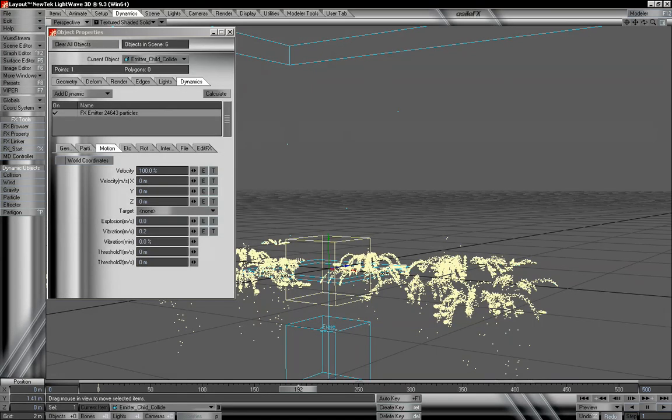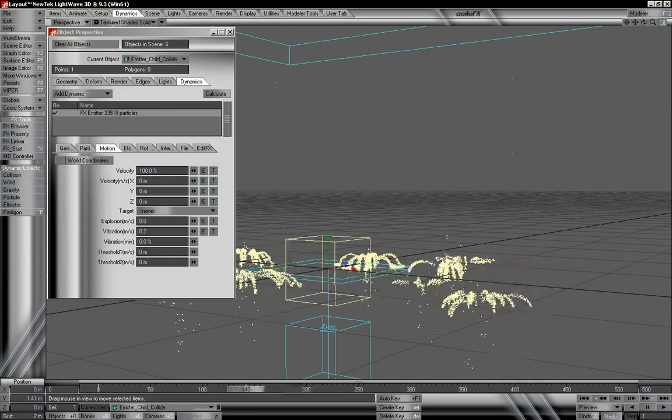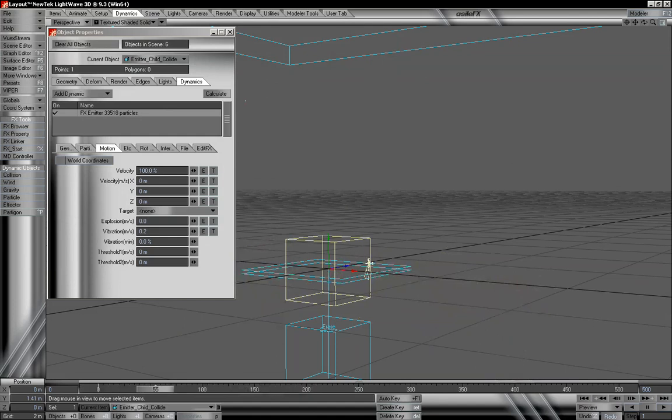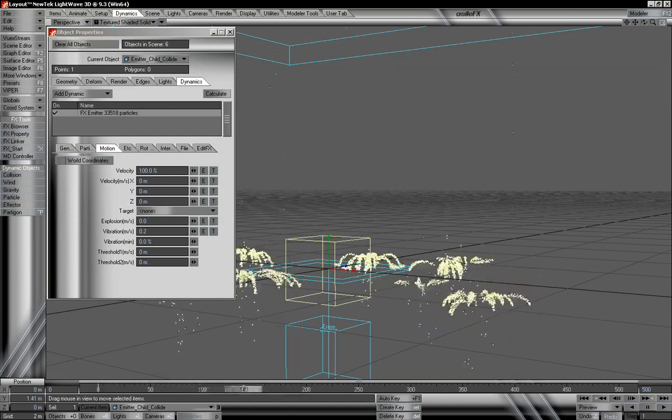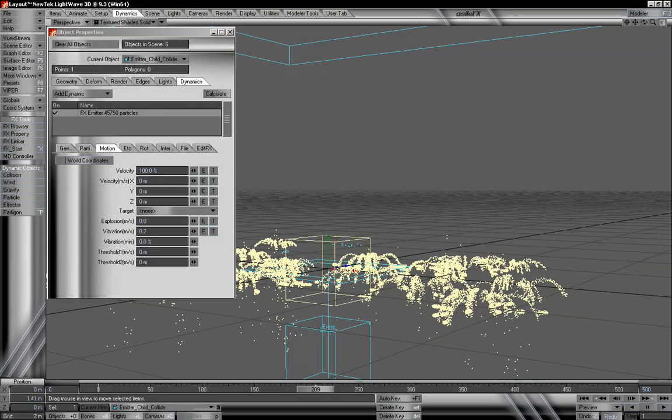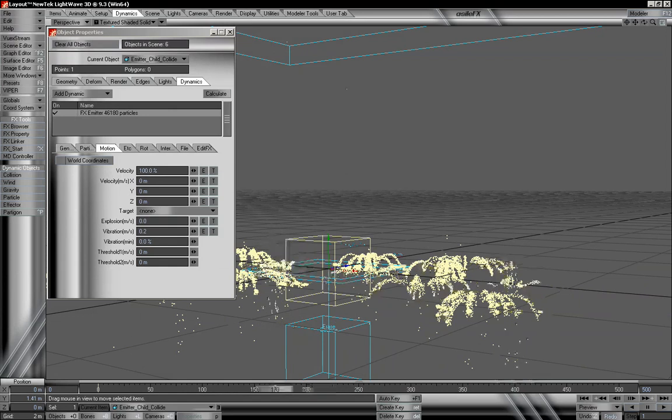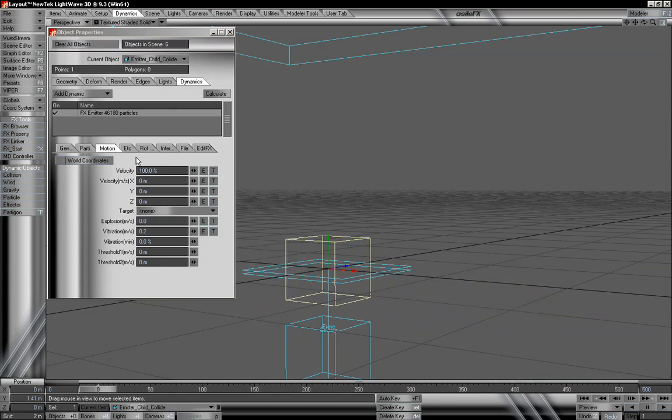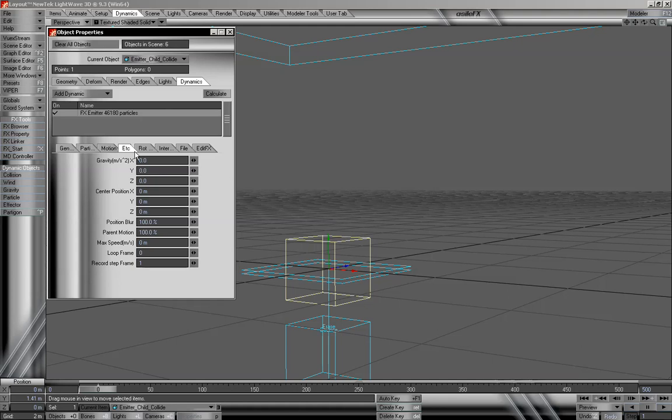And that does look a little bit better. And of course, we could always add in other wind effects if we wanted to add maybe a little bit of turbulence or have a little more gravity. And if this is going to be smoke, we might want to have the particles start to move upward. So what I can do is either create a new gravity object, or we can use the gravity option within this particle to make it start to travel upward as smoke would.